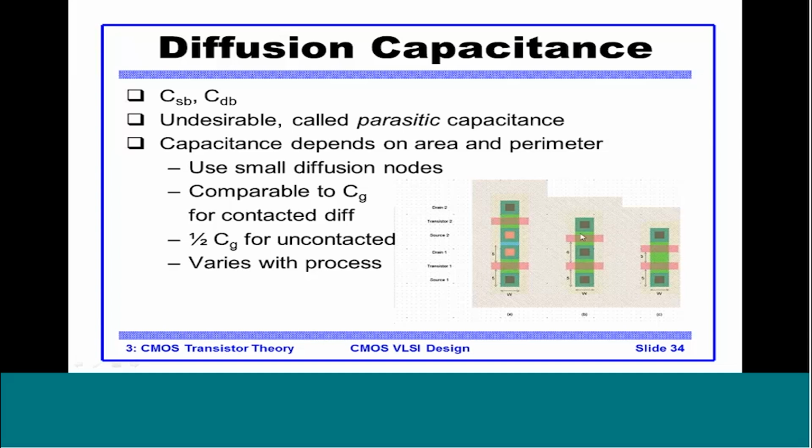So this will show comparatively less parasitic capacitance compared to A, because the diffusion node is made smaller. In the third case, the contact is removed from the diffusion region, and since the contact is removed, the width can also be decreased, that is the node can be made still smaller. So C will have still less parasitic capacitance.